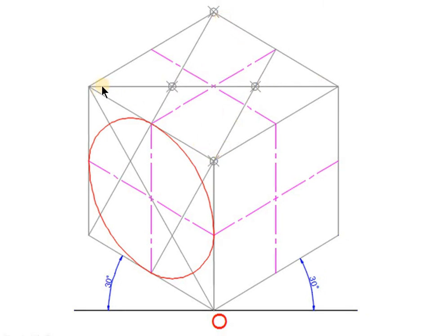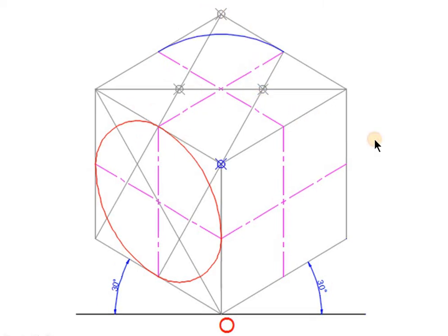So make sure that there will be 2 centers inside the parallelogram on the diagonal. Okay, you remember what I said? You have to check there are 2 centers, one is here, another here, 2 centers on the longest diagonal inside the parallelogram, and then the remaining corners are those 2, here the 3rd circle center, and here the 4th center. So you can create 4 centers here to draw the ellipse, and we'll start drawing the ellipse now.